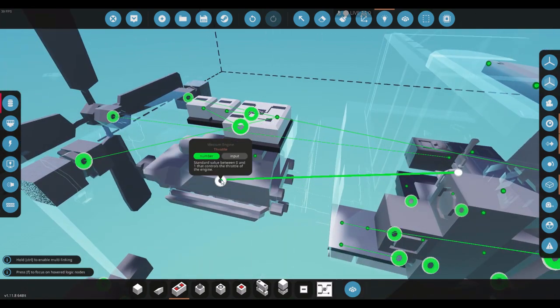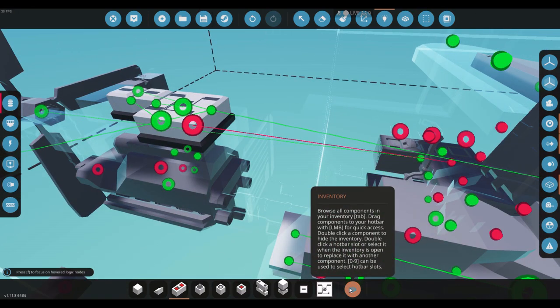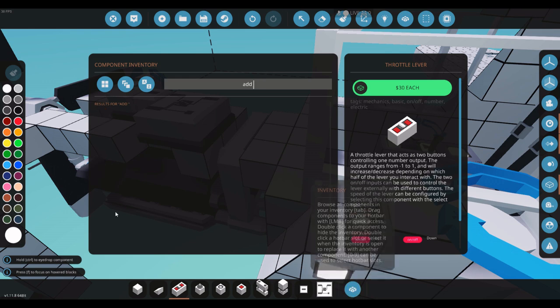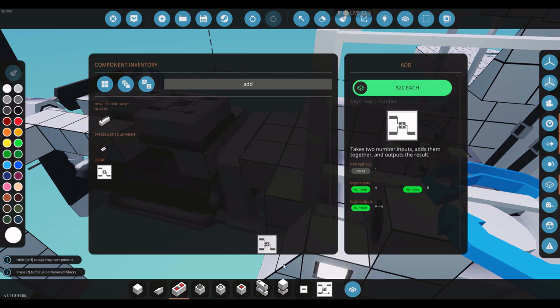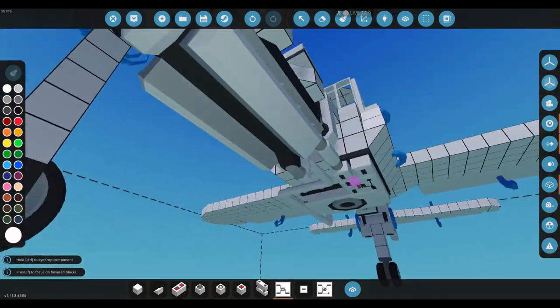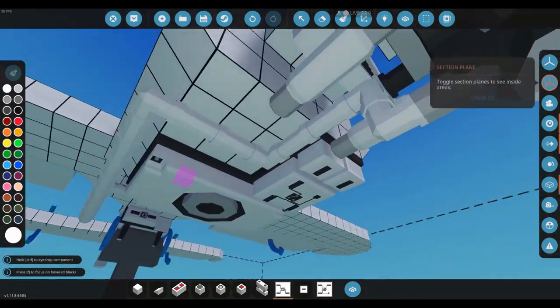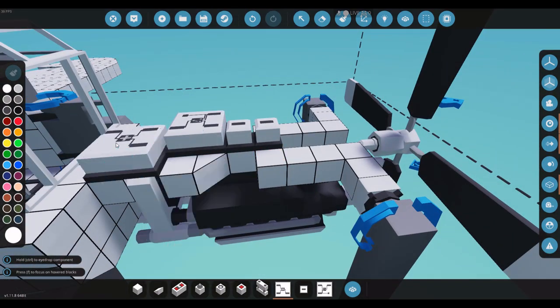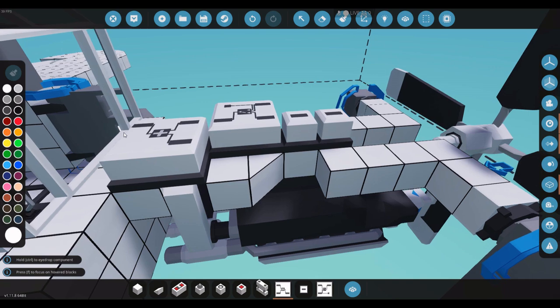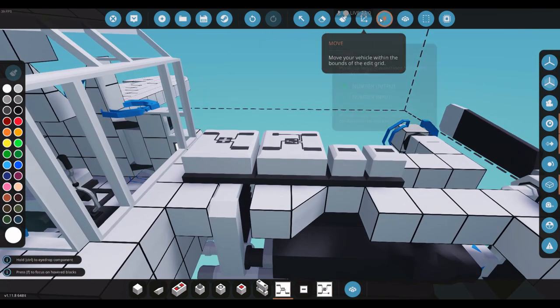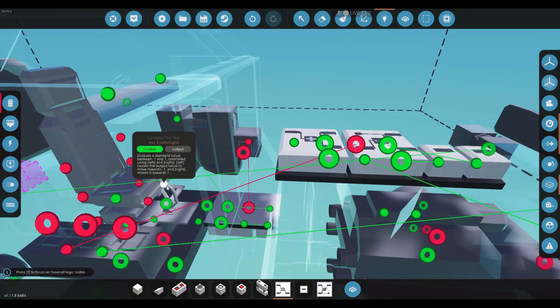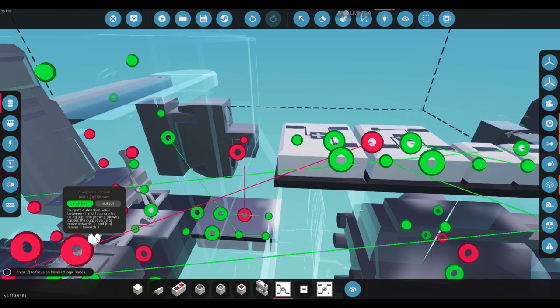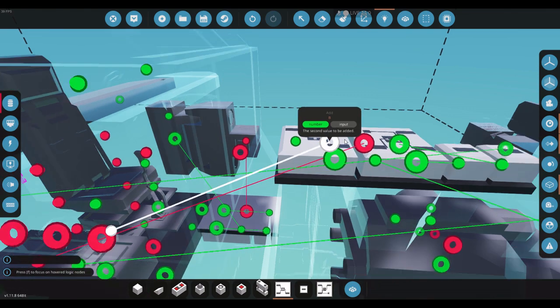Now, instead of putting it directly into here, we actually need what's referred to as an add block. This is the system that allows us to do a speed hold system that'll also control the throttle. The thing is, you also want to be able to control the throttle manually, so this will allow us to do both options. So we're going to put our add block here. This will be for the engine. I'm going to click up and down arrow, and we're going to put that here.